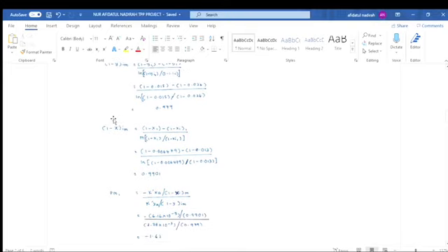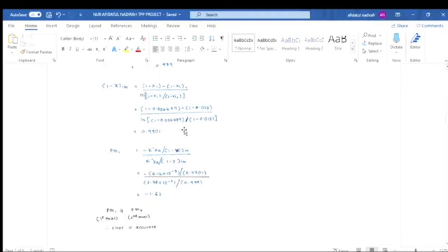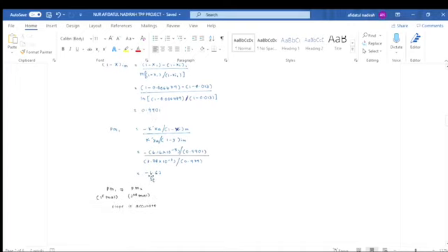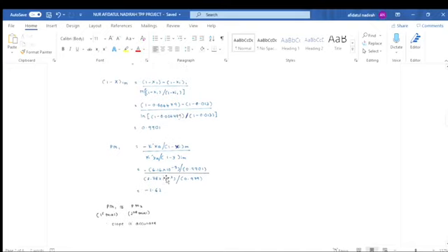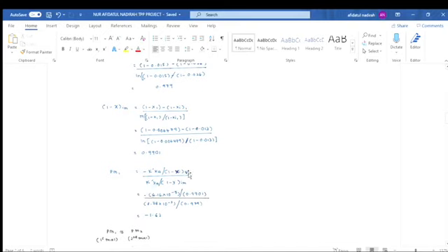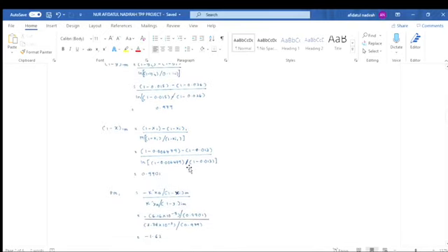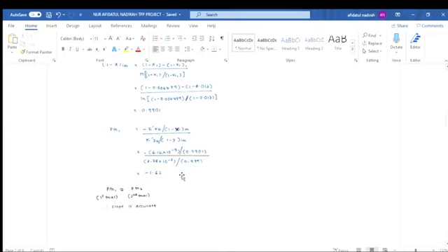Same goes for the 1 minus xi1 part, which is xi1 from the graph and x1 from the question. After we substitute the values 0.979 and 0.9901, we get the slope of PM1 using the original equation is negative 1.62. As the value of PM1 using the second trial and first trial is so close, we can consider it accurate enough.